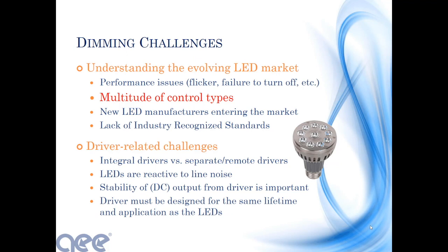Fluorescent ballasts, you can replace the same wattage with the same wattage because UL had testing that said a 32 watt ballast can only put out X amount of heat. So if you replace it with that same ballast that meets UL, you're fine, you're not going to burn the building down, right? They didn't have that with LEDs. There is a new type, a Class P type of driver, that is now just coming out. That standard has just come out saying that if you replace a Class P driver with a Class P driver, you're not in violation of UL.